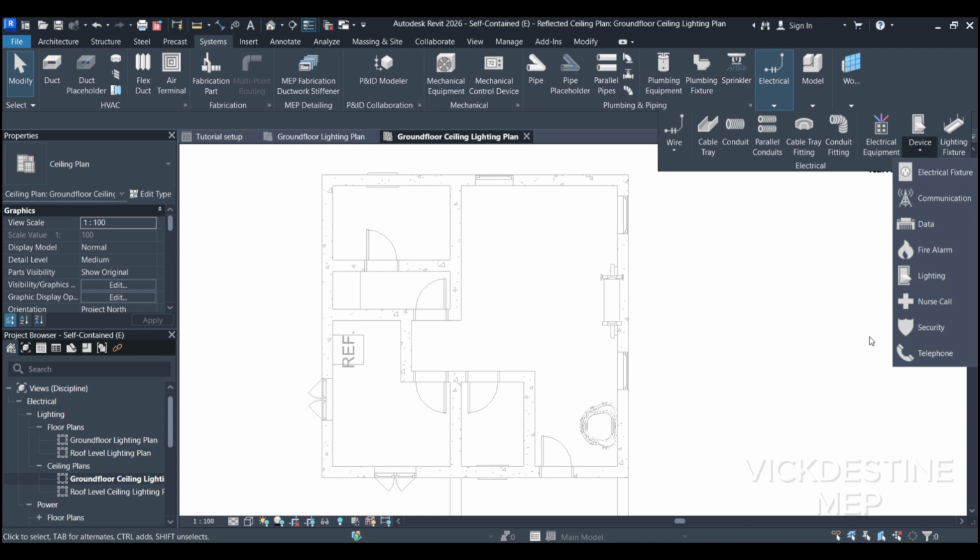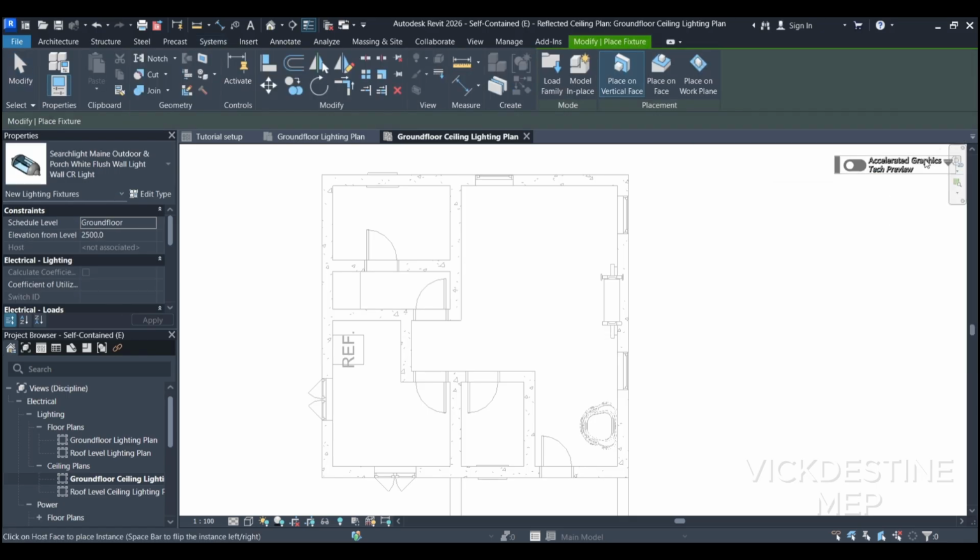The only confusion that you might have here is that the way you know it conventionally might not be what you have here in Revit. Lighting is basically telling you about switches. Then we have electrical features, which is the same thing as your wall outlet. When you want to place a light, your light bulb, where you go is under this lighting feature. So you click on it.